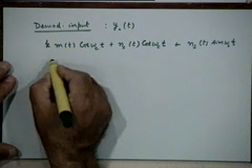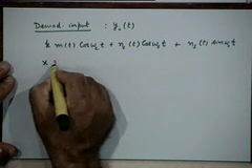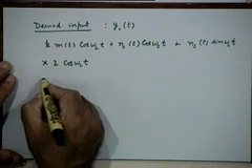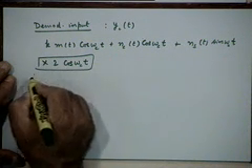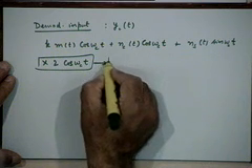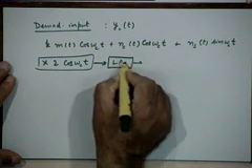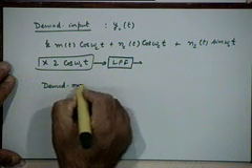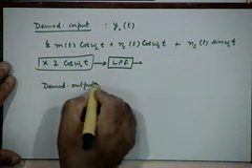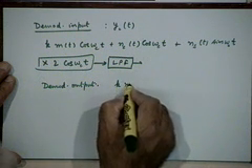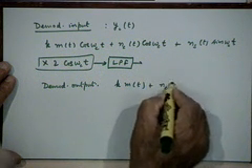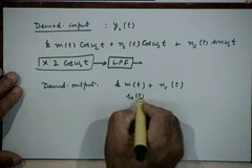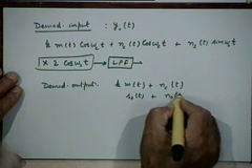So we will multiply this with 2 cosine omega_c t, right? And the demodulator output would be, that's your demodulation operation, followed by low pass filtering. If you do that, your output would be, so you don't have to remember anything, you can always do it from basics, k m(t) plus n_c(t). This is your s_0(t), the signal part of the output, and this is the noise part of the output.